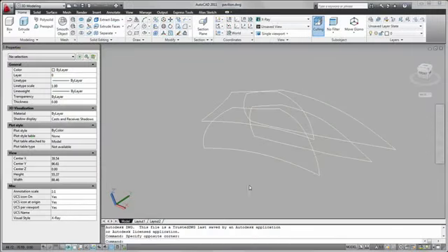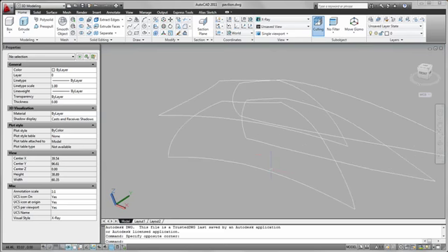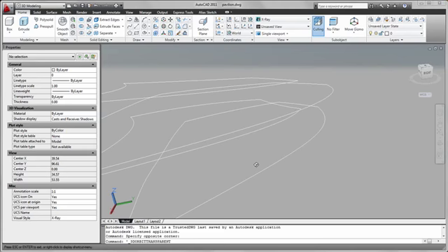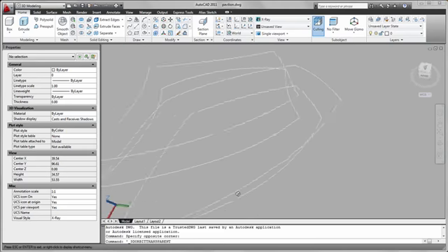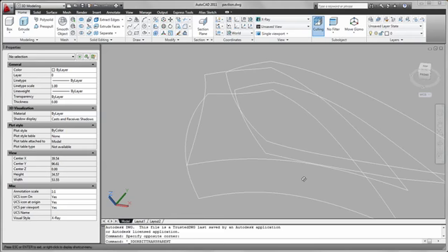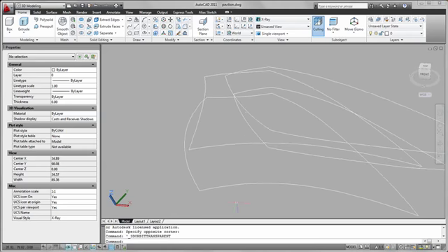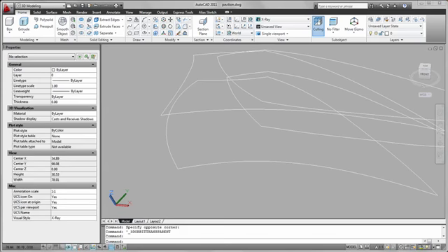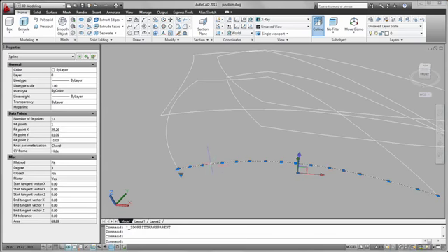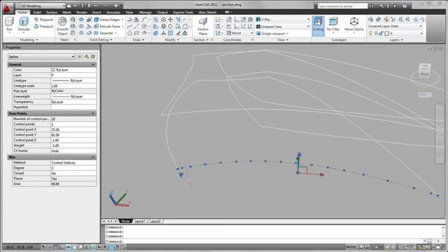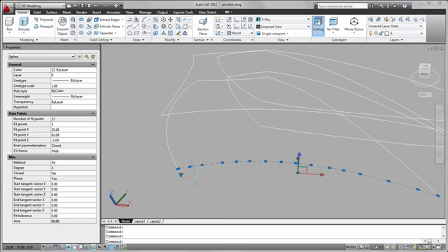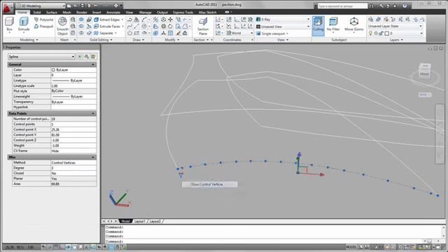In AutoCAD 2011, one of the world's leading 2D and 3D design applications, you can take advantage of a more seamless workflow between initial sketching and 3D modeling. The splines created in Alias Sketch are available as native AutoCAD objects. You can create and edit splines in AutoCAD using fit points or control vertices, and a new grip enables you to easily switch between these methods even after the spline has been created.